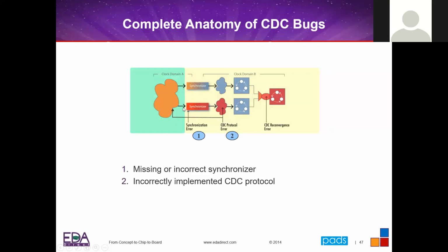On the same clock cycle, I change these 2 signals. So they're in sync with each other right here. And then somewhere down the line, and this could be through some sequential logic, so there could be flip-flops along here, but somewhere down the line, these 2 signals come back together through a logic cone and get sampled.